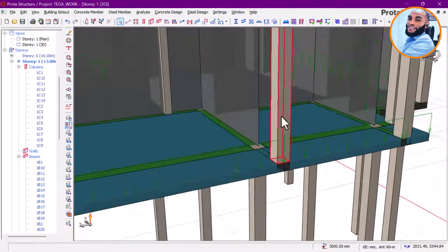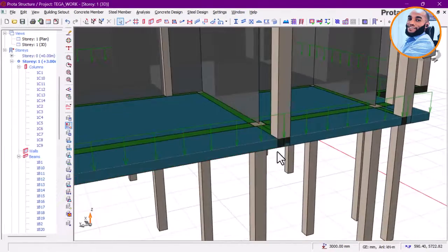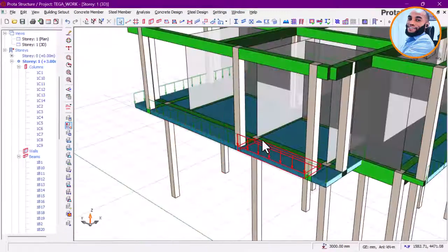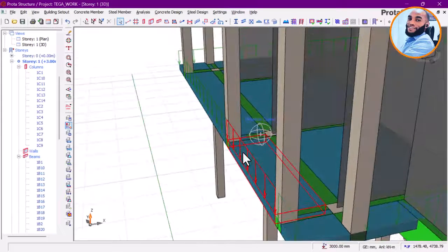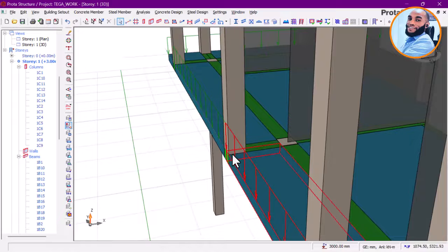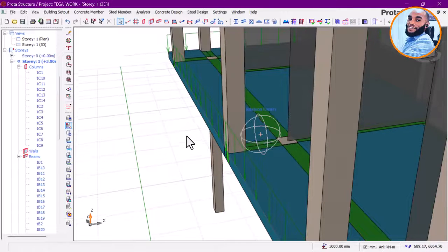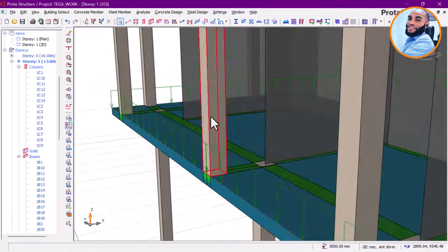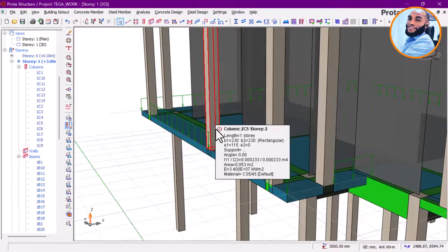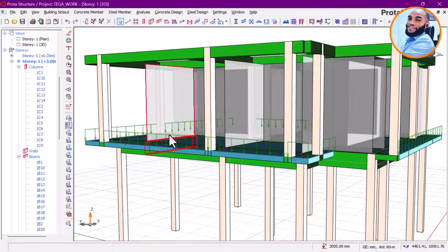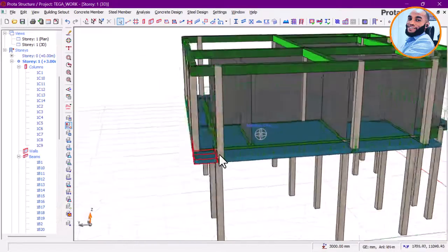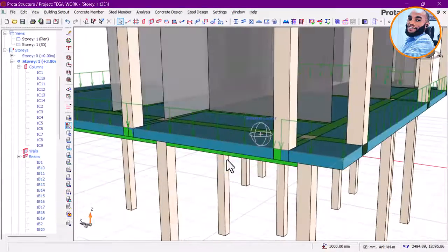To place your column directly on the slab, even if there is a rule that when the slab length of the cantilever is not more than 1 meter or 1.2, you can place your column on the slab and it is okay practically. But theoretically, what is a column meant to do? Transfer load to the beam below and not to the slab directly, except it is a flat slab. But right now this is a solid slab.